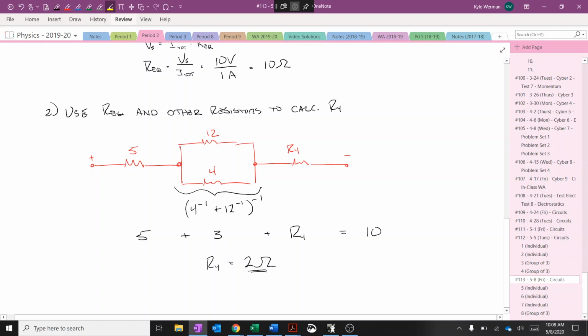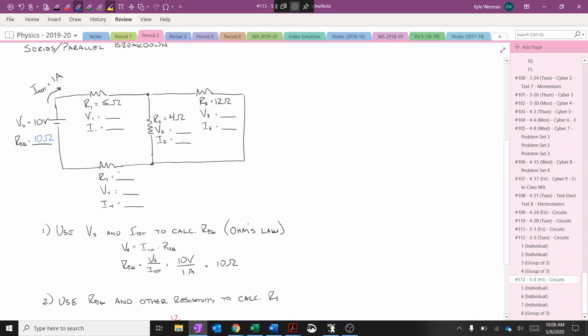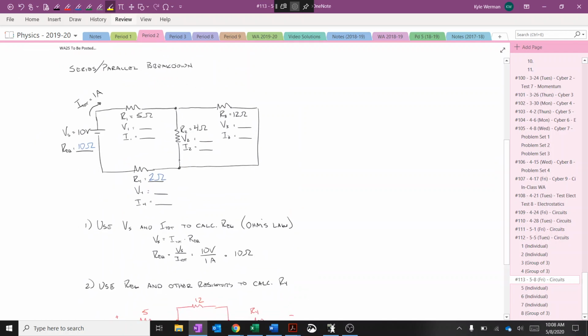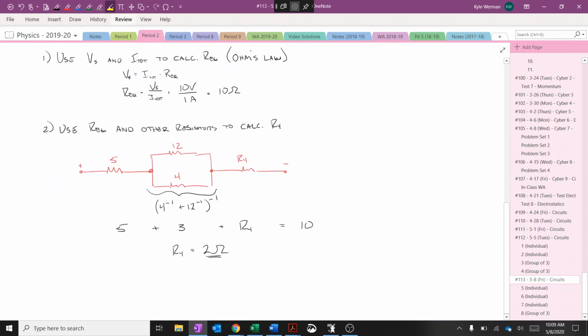All right, so we've basically figured out from the missing pieces that I know R4 is now 2 ohms. So I have all my resistors now, I have my total current. And now let's start looking at those series and parallel rules. So now that we know, again, we could have done this as a first step, but I'm going to use my series current rule. What happens when you have to pass through, series current rule, to fill in I1 and I4.